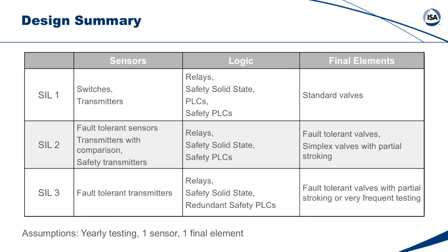The table looks a little different, but the wording, if you understand it, is really the same as the old table. Because SIL 2 could be done with single devices if you know what you're doing. I could select safety-certified devices that, based on the higher level of diagnostics, meet SIL 2, but you still must read the vendor's safety manual in understanding how you have to configure, maintain, proof test, and operate that device. If you don't follow the vendor's manual, it doesn't meet SIL anything.